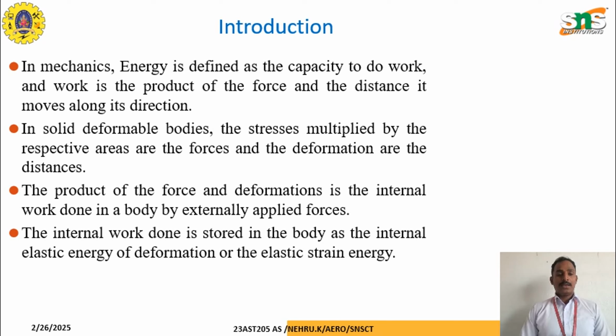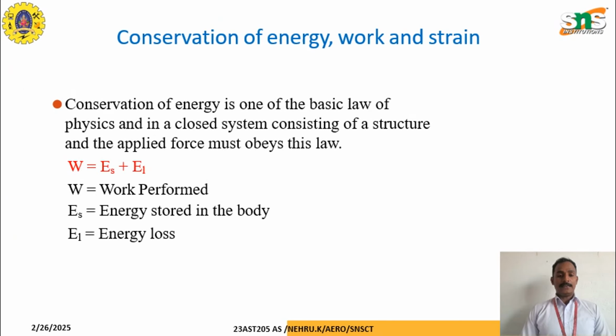So in the introduction, in mechanics, energy is defined as the capacity to do work, and work is the product of force and the distance moved along its direction. In solid deformable bodies, the stresses multiplied by the respective areas give the forces, and the deformation is the distance. The product of this force and deformation is the internal work done in a body by externally applied forces. The internal work done is stored in the body as the internal elastic energy of deformation, or elastic strain energy.